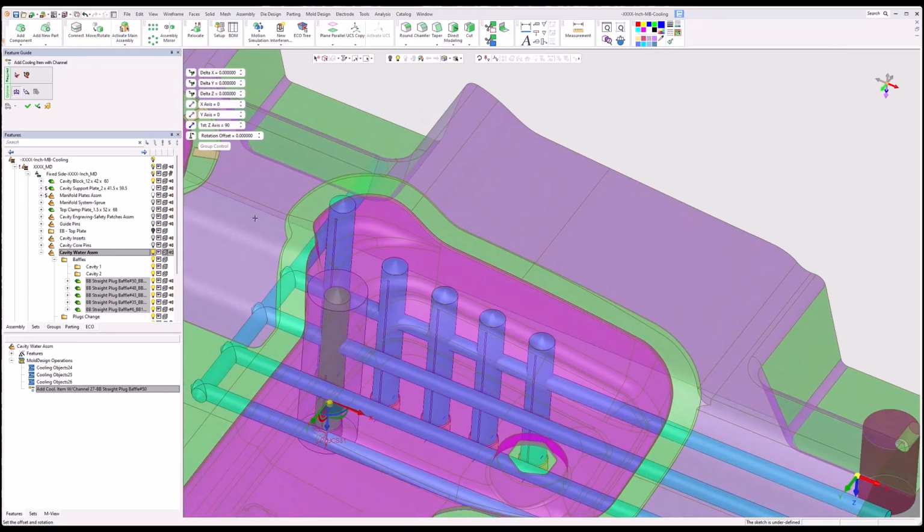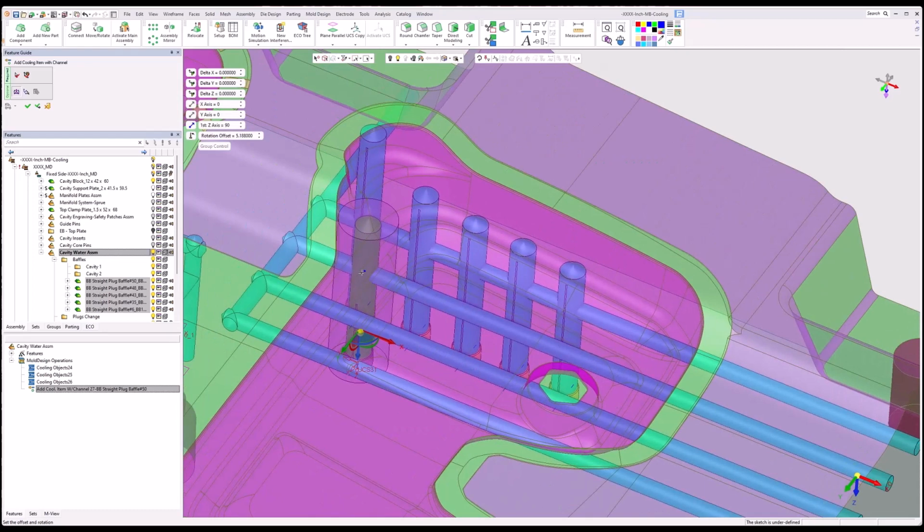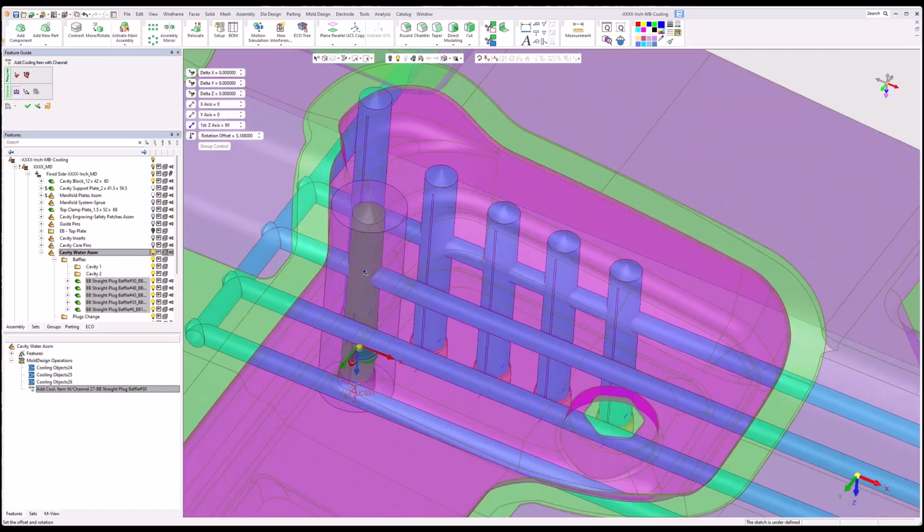We'd like to rotate it. So if I pick this, a rotation point, and I pick the center of that water line, you can see it moves the center here. If I don't do this, it's going to rotate it from the bottom. Now it understands to hold this point and rotate it about that point. And now I can, wrong way, let's go about the X. Yeah.